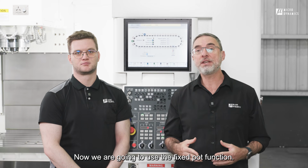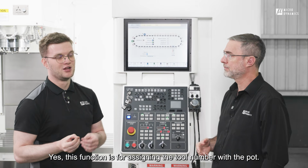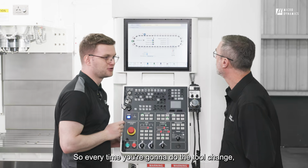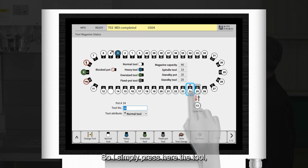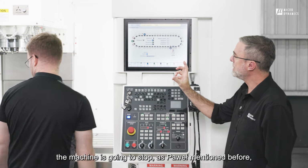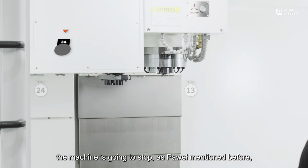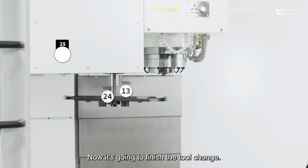Now we are going to use the fix pot function. This function is to assign the tool number to the pot. So every time you do the tool change, it makes sure that it goes to the same pot. So I simply press here the tool, fix pot, and apply. Now we have gray in the 24. When we change the tool, the machine is going to stop, as Pavel mentioned before, because it needs to keep pot number 24 empty for this tool. Now it's going to finish the tool change.